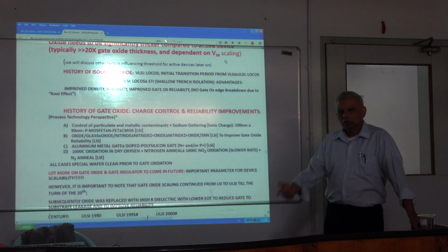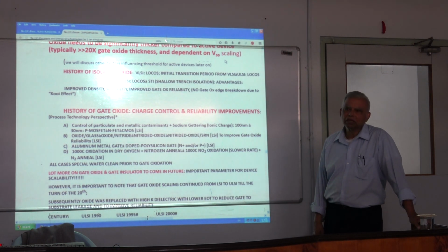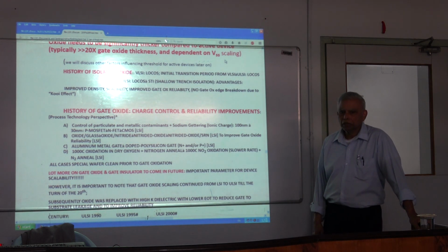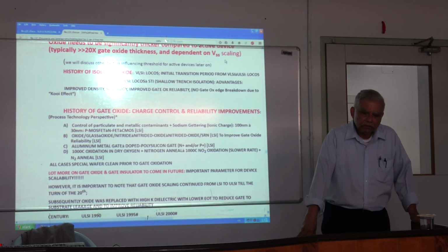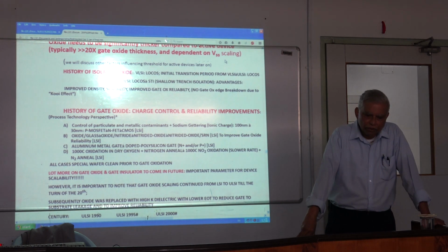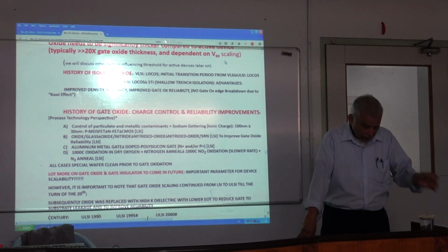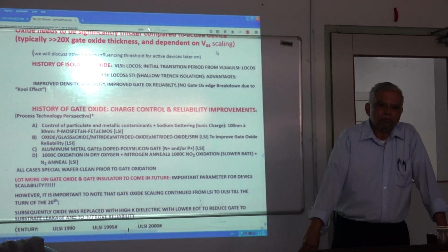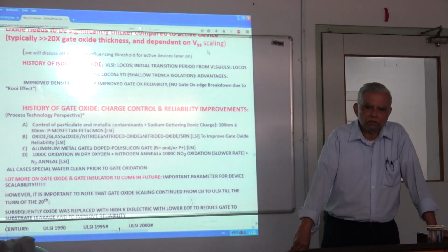That's why, well, we knew that long before the oxide limits, so we used to make nitride in oxide for stability in the thickness range. So my last, can't remember exactly, but the last technology that I directly developed for IBM, that was back in 1990, a bi-CMOS technology, it's the one and only bi-CMOS technology at that point.